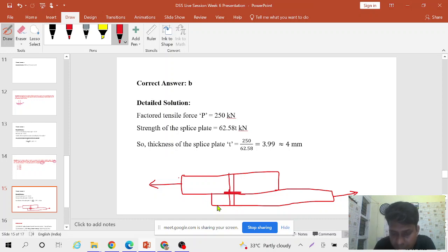Yes sir. So I think the minimum value is used for both of them, although it is said that shear is there. That's why they have not used the term bearing. It might happen that in these types of connections we are not providing bolts in double shear.